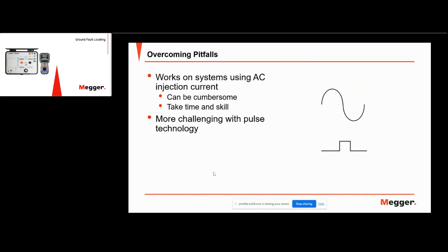One is drawing 2 milliamps, the other's drawing 2 milliamps, and the third's drawing 1 milliamp. Which one has the fault? Well, the problem is you may find out that 2 of them are just drawing current because of high leakage capacitance. And this is why we need to figure out which one is the real fault.